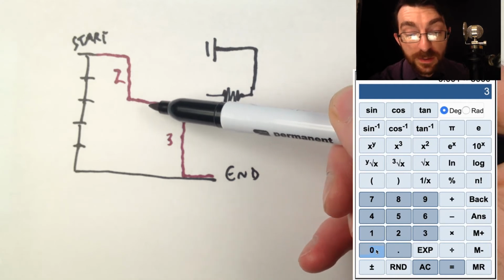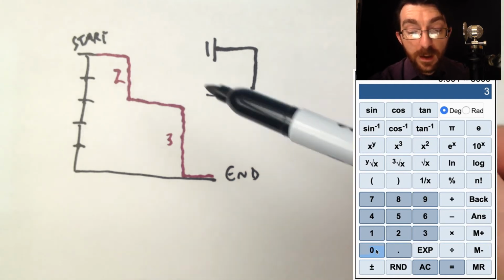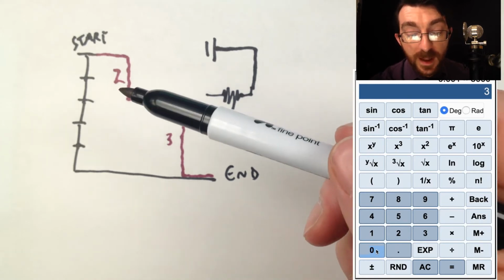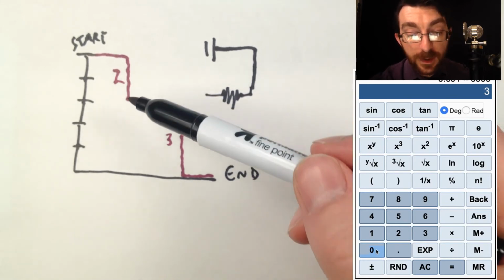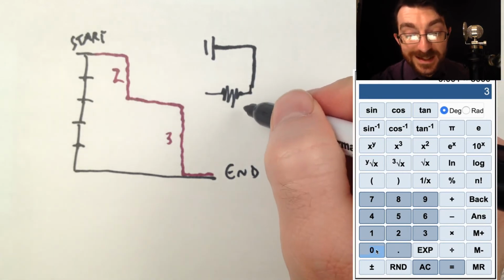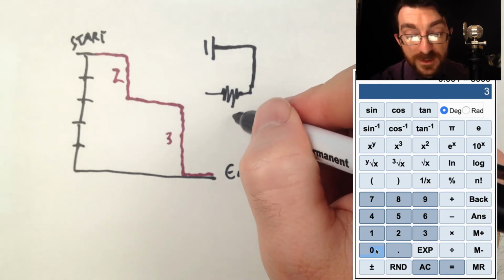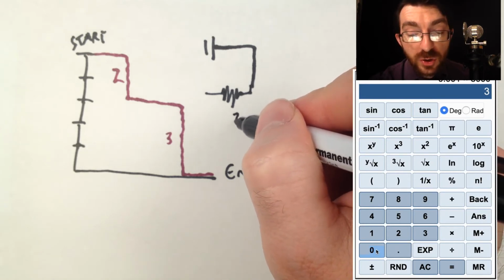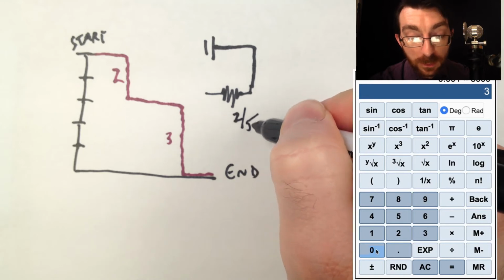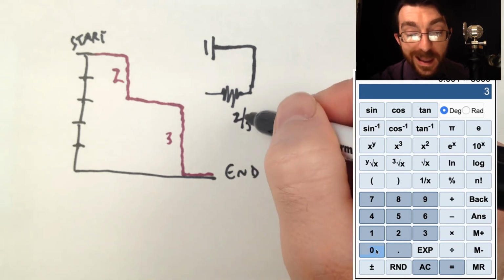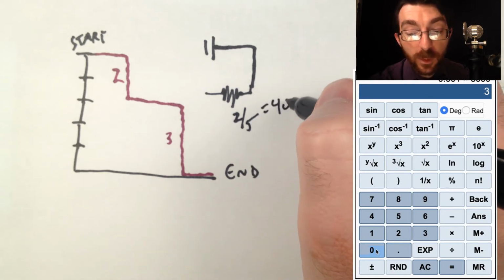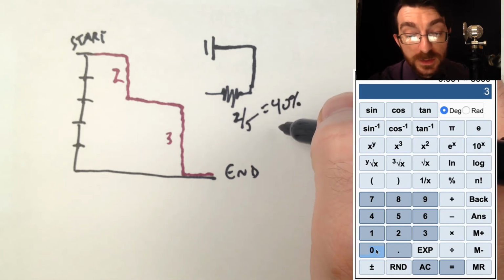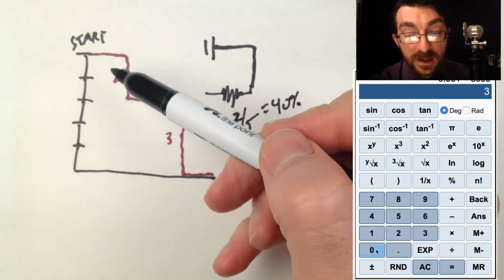Afterwards, you're only down to 3 because 2 of them are gone. That resistor is equivalent to that step. And the height of that step corresponds to the resistance of this resistor, because this was not specifically 2, but 2 out of the total. Okay? It's going to cut 40% of the voltage of the battery. So if this went up to 50, this would have been 20.